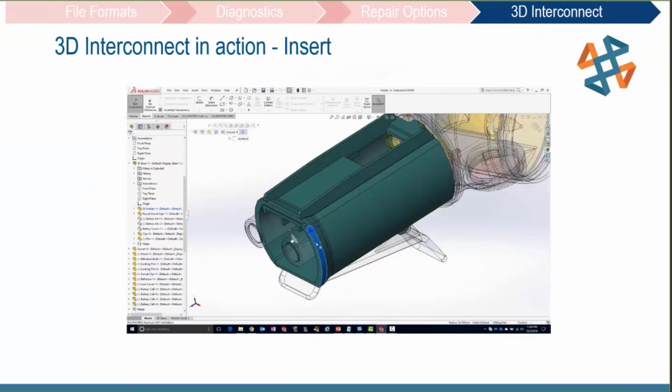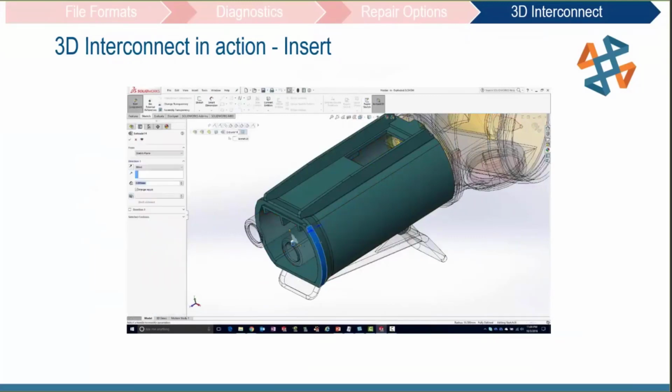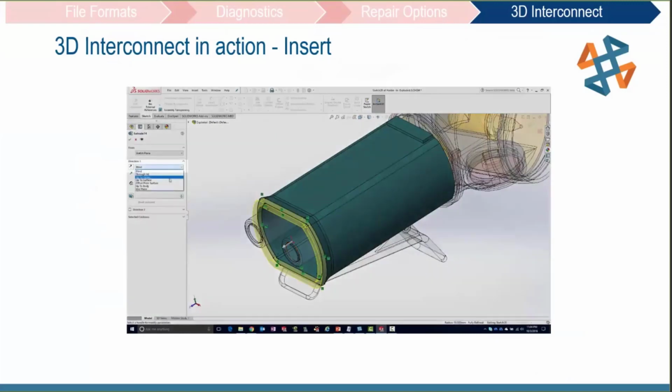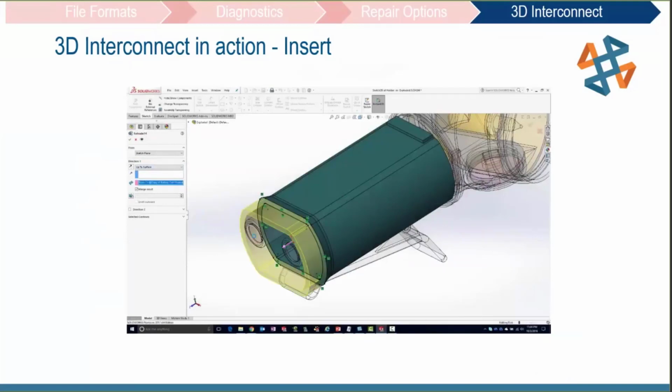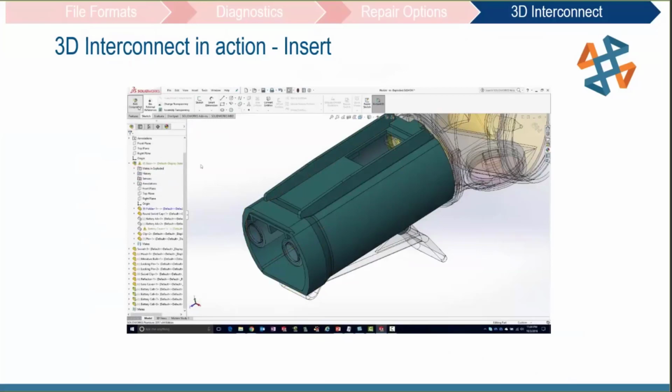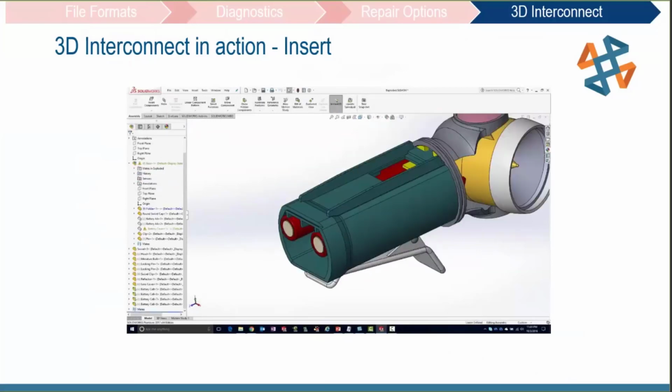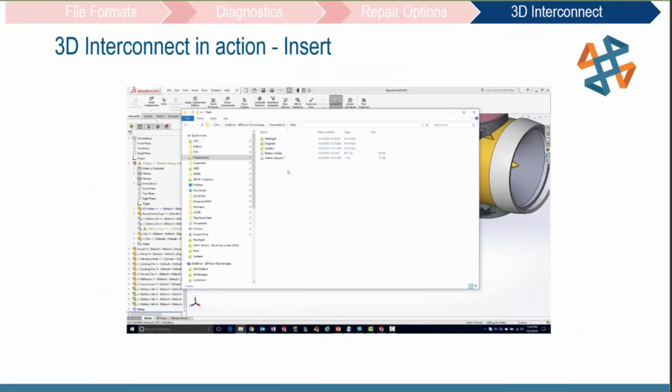But what I'm doing now is I'm editing this part, and I'm changing its extrude definition. I'm going to say send that extrusion all the way up to a surface of this new non-SolidWorks part. So really, you wouldn't do this without this functionality, because why would I need an extrude to go up to a dumb solid? Right? This only helps if changes might occur. So now to simulate a change, I'm just going to copy and paste a different version of the battery on top of itself. So this simulates some other user opening, modifying, and resaving that. Basically, it has a new save date.